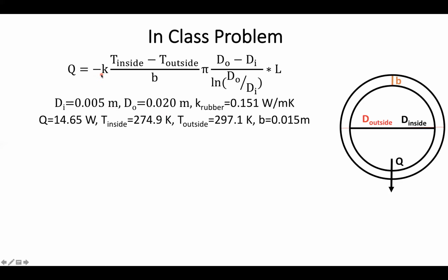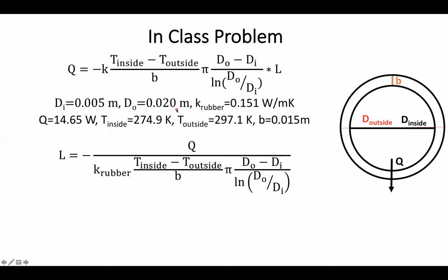So when we end up expressing this, we have our classic form of here's my coefficient, difference in temperature, and the thickness of the material. And what I've essentially done here is I multiplied my flux, which is this term, times my area. So when we do this, we can plug in our equations and rearrange to solve for L. So again, L is going to be related to the actual heat transfer divided by all the other parameters.